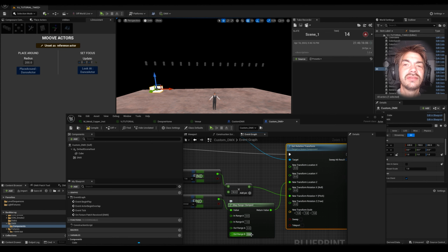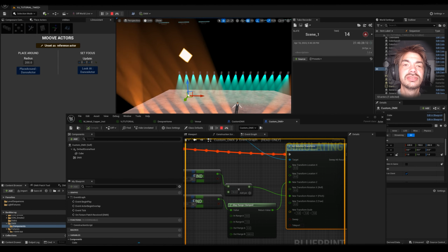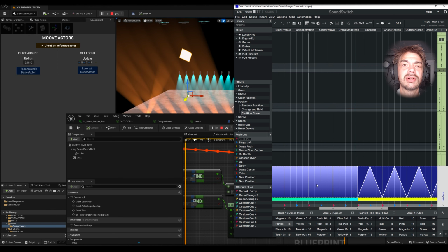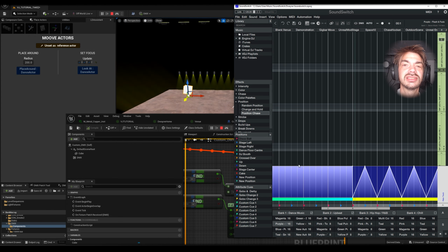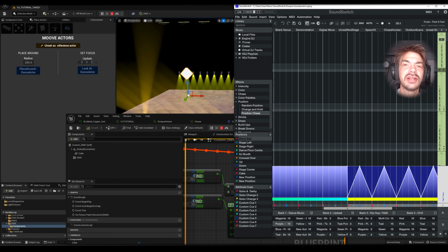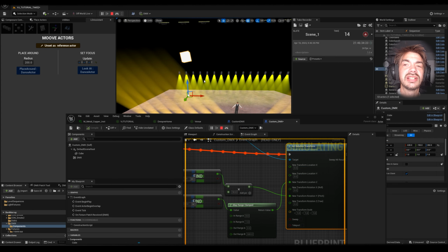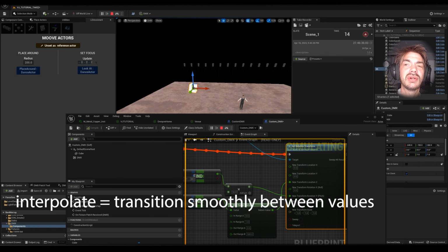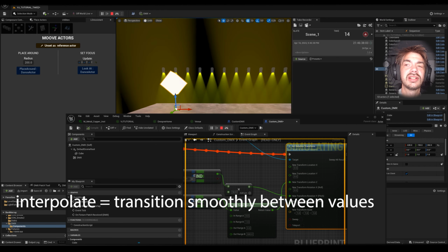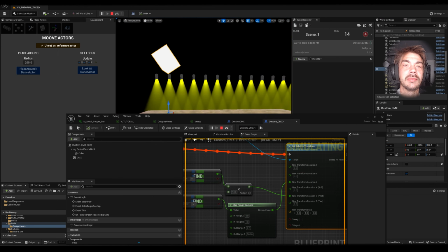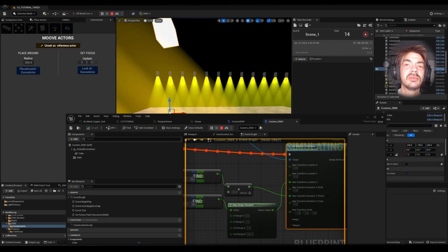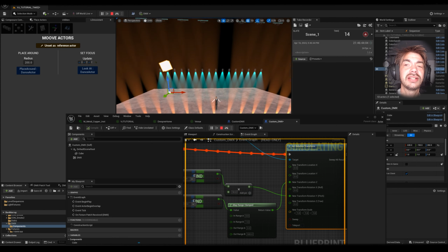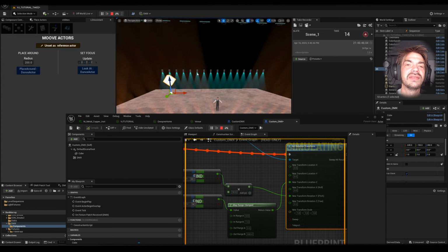You can see one visual glitch you might encounter using this technique where your dimmer value jumps from 100 to 0 or vice versa, and your object just teleports from one spot to another. There should be some way to interpolate to your value over time, like is built into the DMX Fixture plugin, but I couldn't make it work. If you want smooth movements, stick to pan tilt channels as they're less likely to jump around in value.